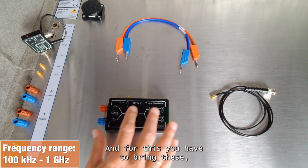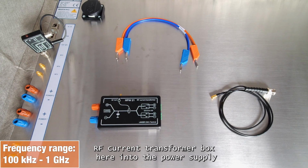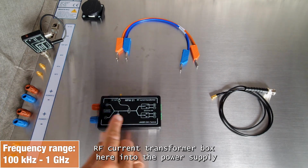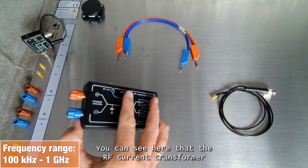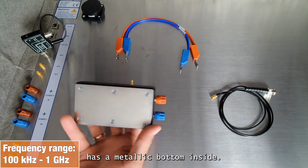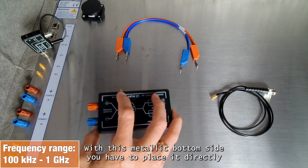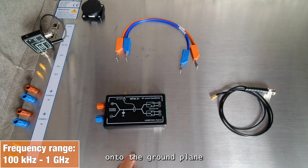And for this, you have to bring this RF current transformer box here into the power supply of the device under test. You can see here that the RF current transformer has a metallic bottom side, and with this metallic bottom side you have to place it directly onto the ground plane.